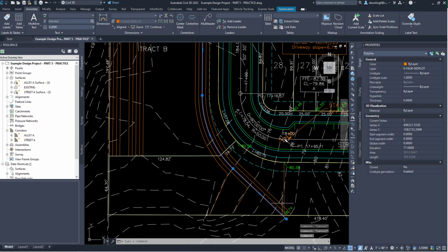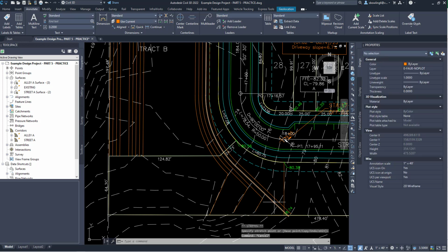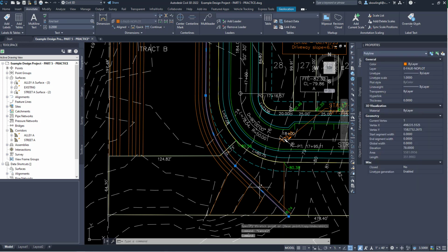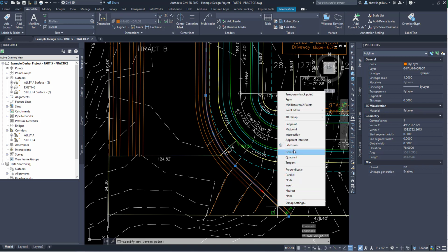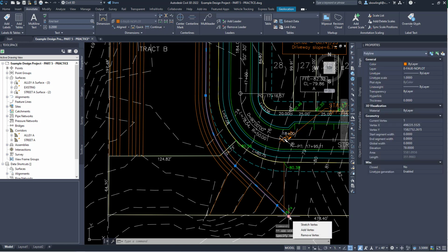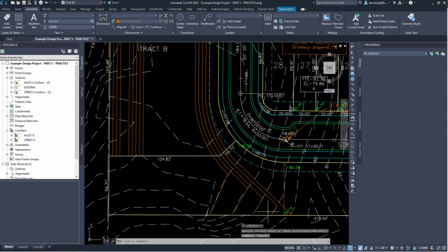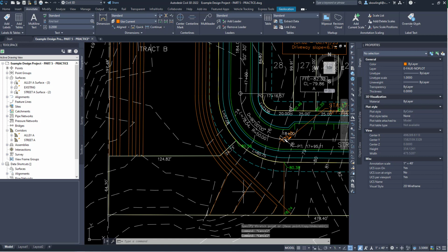All I'm doing is giving myself the opportunity to tie back down to grade, which is extremely important when you're doing projects and making sure that all the elevations tie in. I'm using natural ground, existing ground, to make sure that my grades tie in. Now I'll have to give these contours a fillet radius. I'm going to say 10, just to make it look a little smoother. And I'm using 10 on all of them.